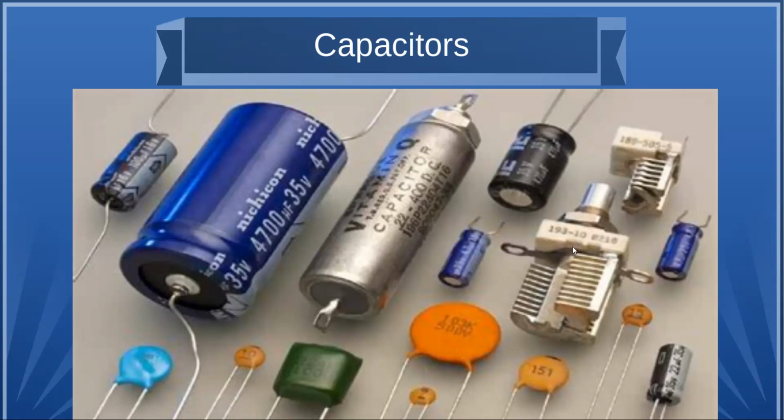And they'll still hold a substantial charge even if disconnected from a power source. Yeah, if you had one in a transmitter or a matching network for a high power amplifier, and you got a few thousand volts across that capacitor, it's got a little charge. The old cameras, that's how the flash cubes went off, the flash cubes were powered by a capacitor.